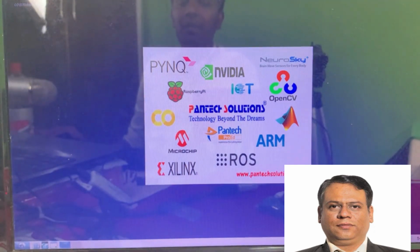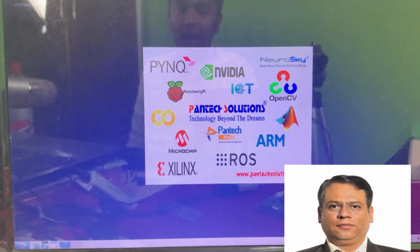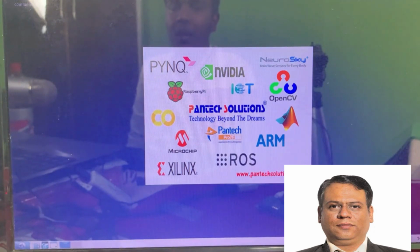On the display, first of all, go to the bottom right corner. There will be a tower symbol or an X mark symbol. Where it shows disconnect, you just click it, and that icon will look like a monitor kind of symbol. Then click it again and look for the Wi-Fi address present in your home, and connect to it. After connecting, you can see the tower symbol there, which represents that this Raspberry Pi OS is connected to the network.